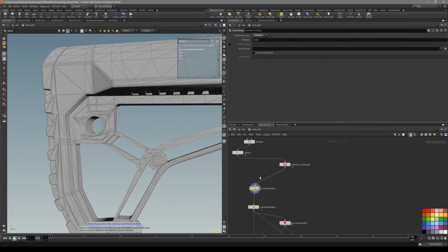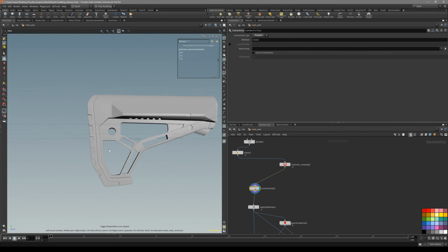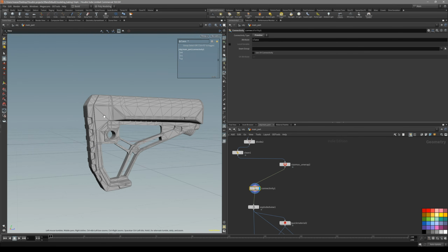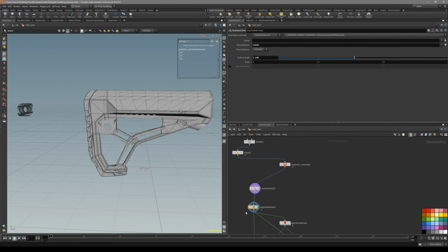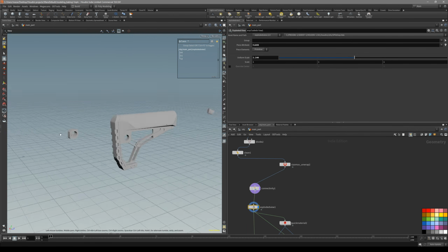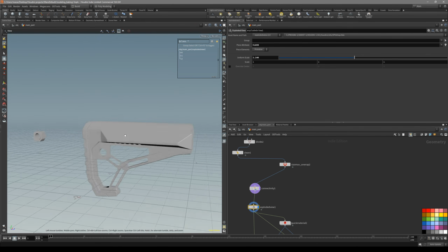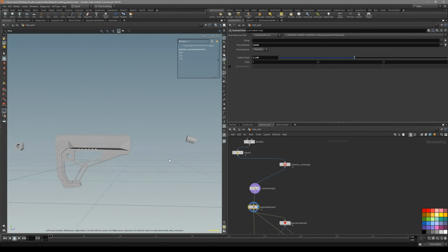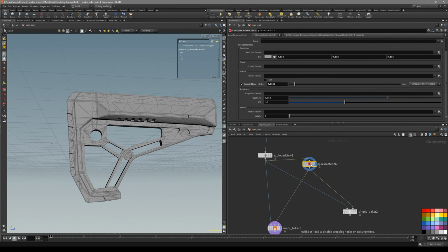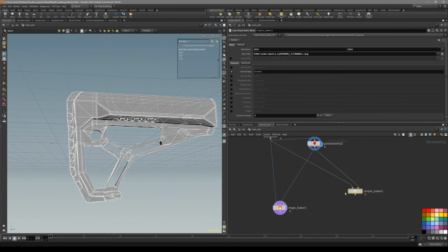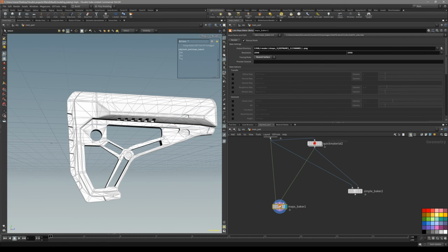Once you have UV unwrapped, we have this connectivity node, which is basically for when you start baking. You want every separate part, every part that's not connected with each other, to be on its own part of the geometry. So then it would not intersect with each other and would not create artifacts. So make sure it's exploded. Once you have our quick material added, we can either go with the simple baker or the mouse baker.